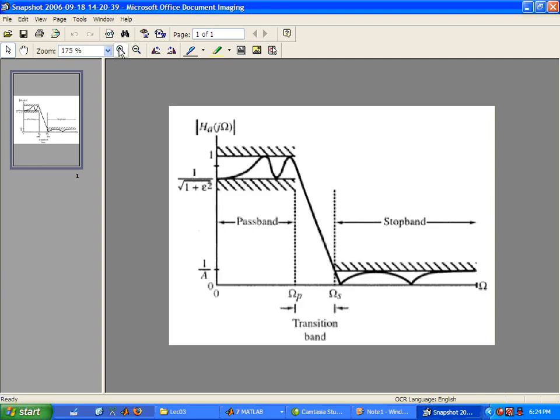All right. So this is your typical low-pass filter, and it's in the analog domain. Essentially, you build an anti-aliasing filter because you want to get rid of the high frequencies before you sample. If you don't get rid of the high frequencies, you alias. This we know. Your typical low-pass filter has a pass band and a stop band. Within the pass band, you define something called the ripple. You say, I'm okay with the amplitude changing a little bit within the pass band.